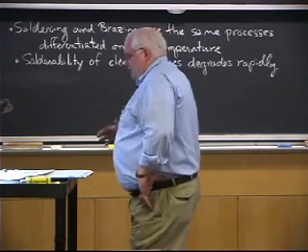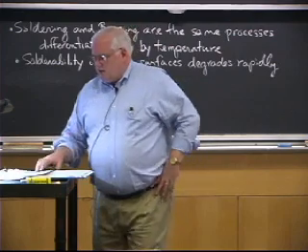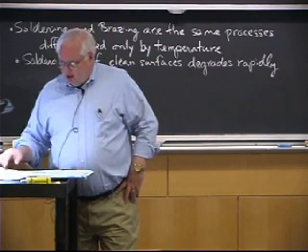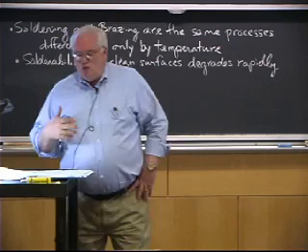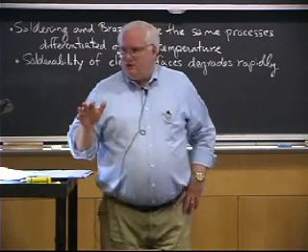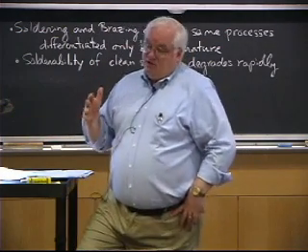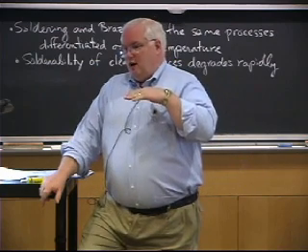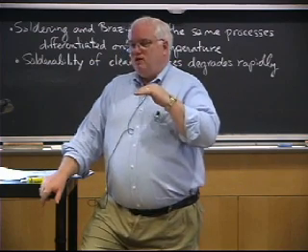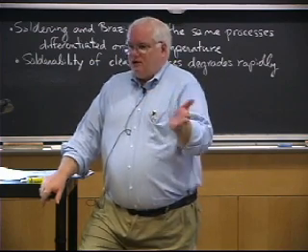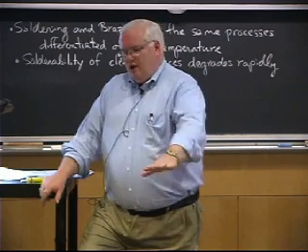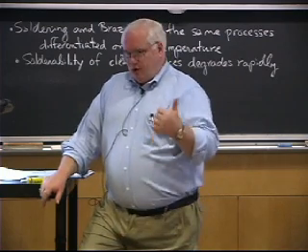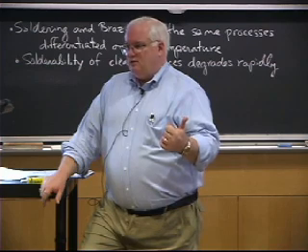And I also spent a fair amount of time talking about cleanliness of solder joints and the fact that they degrade rapidly over time. You grow surface oxides within minutes. Actually, we know you grow contamination films within microseconds and nanoseconds. The Langmuir is 10 to the minus 8 atmosphere seconds. You'll get a monolayer of surface contamination at 1 atmosphere pressure in 10 to the minus 8 seconds.